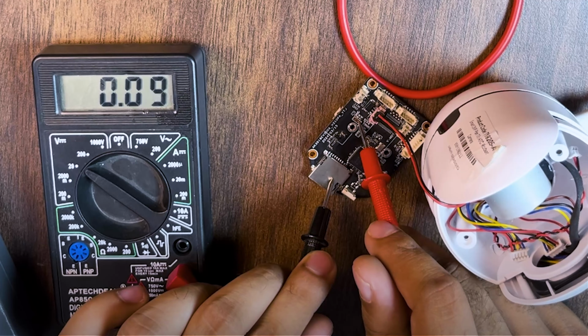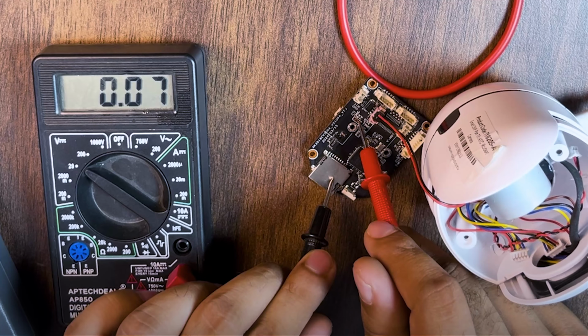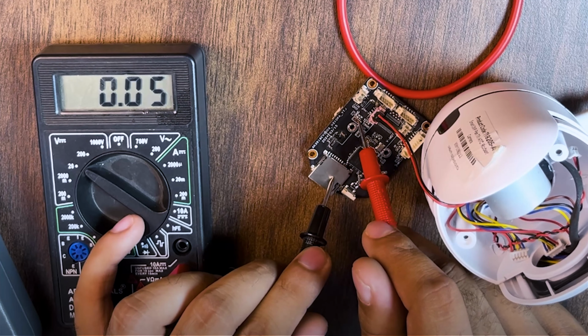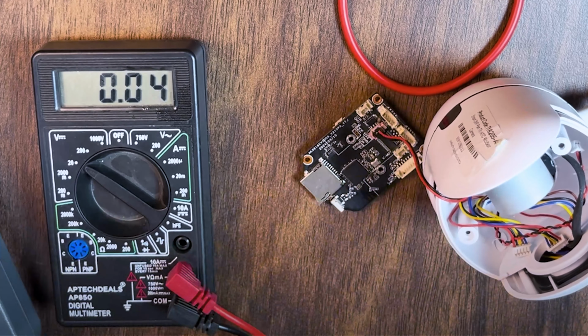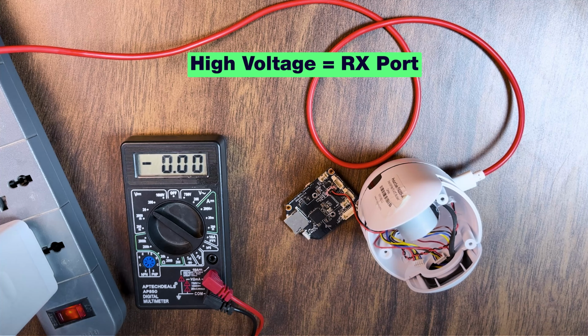Now, the thing that could be happening right now is that values are quickly fluctuating on the TX port, which my current reader, the multimeter, is not able to actually calculate. It's showing the average voltage, and the average continuous voltage is coming out to be 0.0, 0.02, and so forth. With RX, we saw the average voltage being held high. This could allow us to conclude that if it's being held high, the port is RX, and if it's being held low, the port is TX.